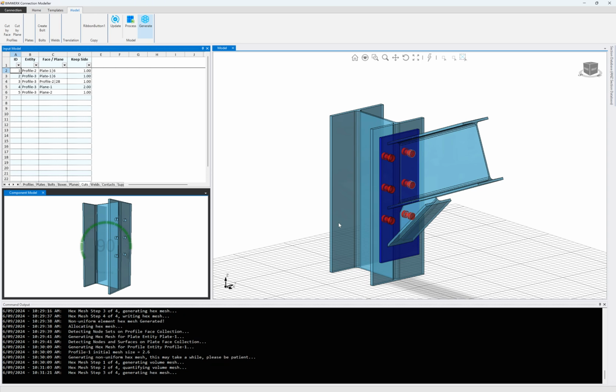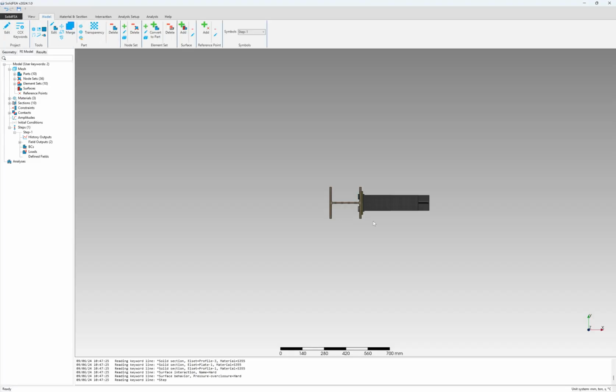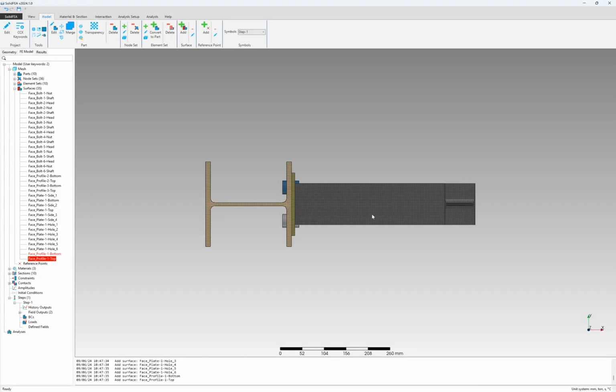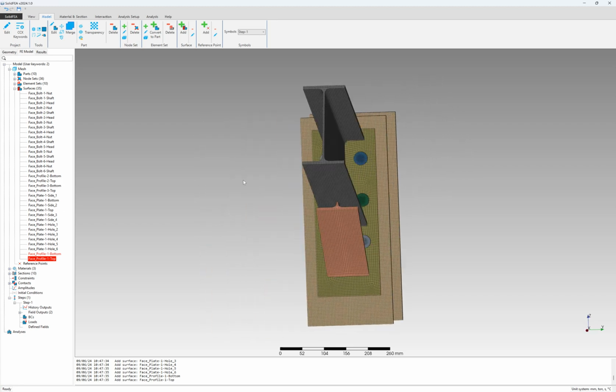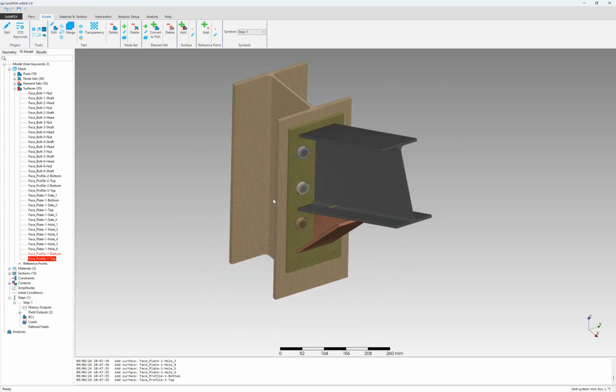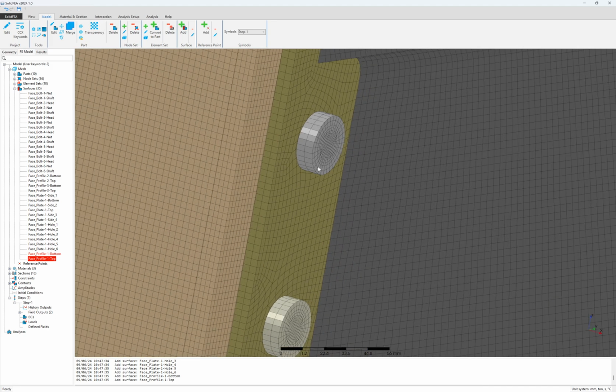The overall process took around 10 minutes for the complete hex mesh model generation, but it's fully automatic. This is quite a hot topic, how you achieve a high quality hexahedral mesh automatically, and it seems like we've been able to do this reasonably well, but some further development is underway to improve that further.